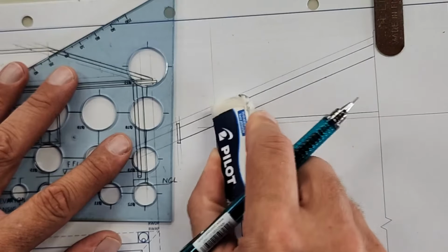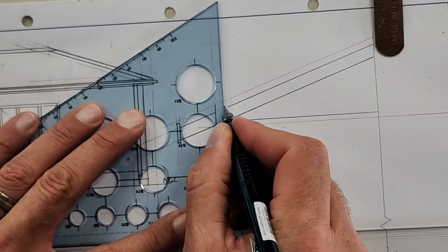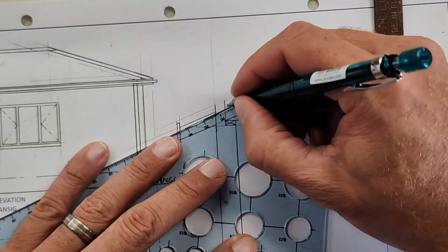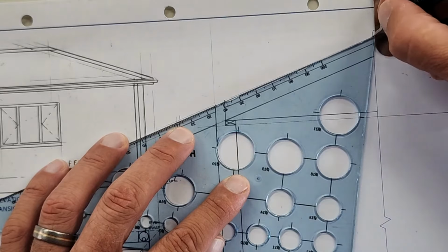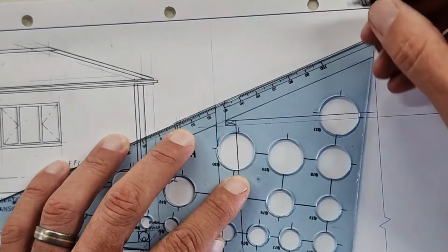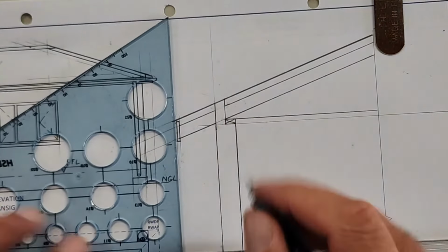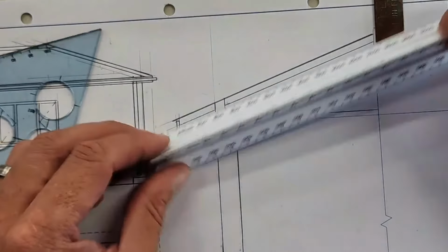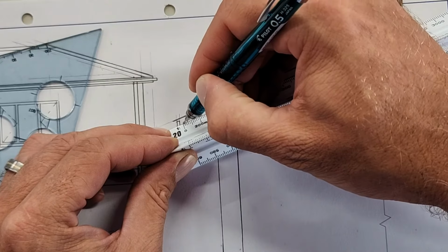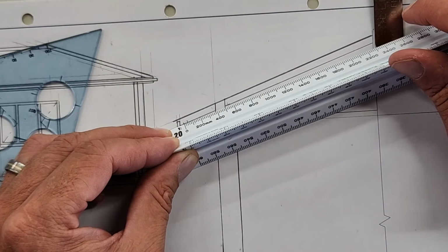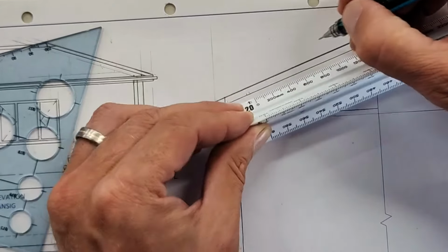Sorry, there's actually beam filling here. I keep forgetting that part. So this wall is going to go up to underneath there. Up to underneath that. Okay, there's my roof sheeting. Do a double line. Okay, then our purlins. The first one is right here. 75. What's the center to center spacing on that purlin? 750. 750, that's 700 right there. Another one.